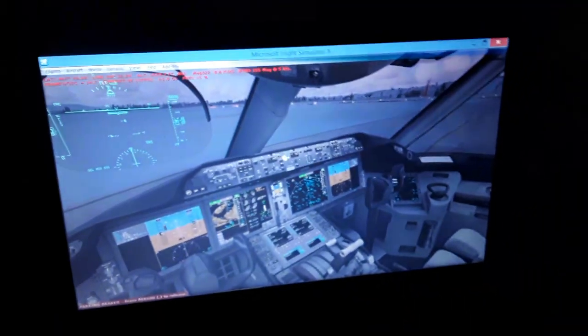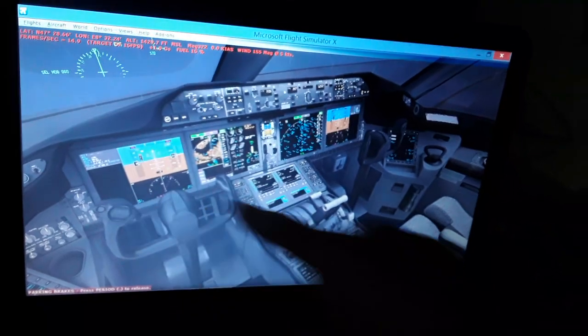We have also, both in the Airbus and the Boeing, the automatic trim of the aircraft when we fly from the flight control computers. They can estimate from the flight management computer, also the autopilot flight director system panel, the sensors of the aircraft when it flies, its attitude and what it needs to do to balance the aircraft in the air. So we have the automatic trim. We can use the manual trim all the time here from the Boeing and the Airbus aircraft. So we have the automatic trimming in the Boeing aircraft.